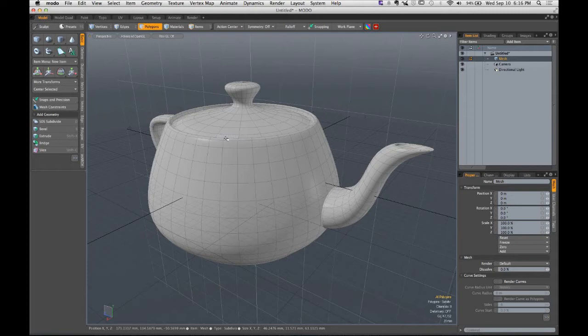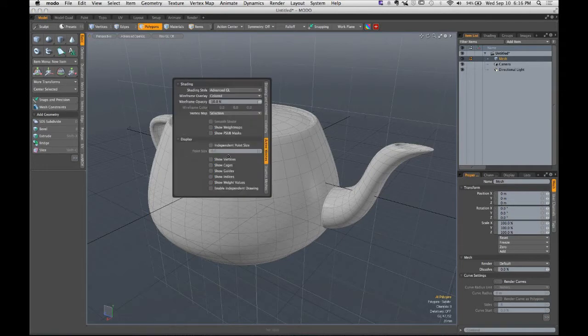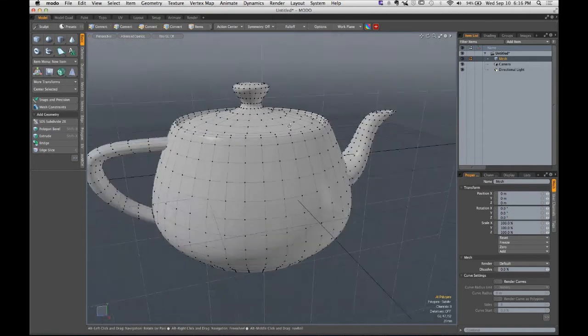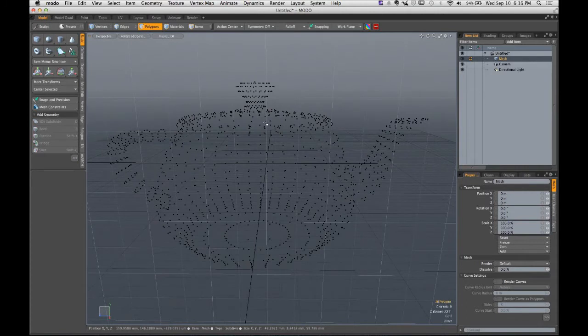Yeah, the traditional backspace key, because that's not going to delete all of the components that are associated with our surface. As an illustration of that, I'm going to turn on the visibility of all my verts on my little piece of geometry here. And then if I hit the backspace key, as you can see, all those verts are still kind of hanging out inside of my scene. This is bad. This is very bad.